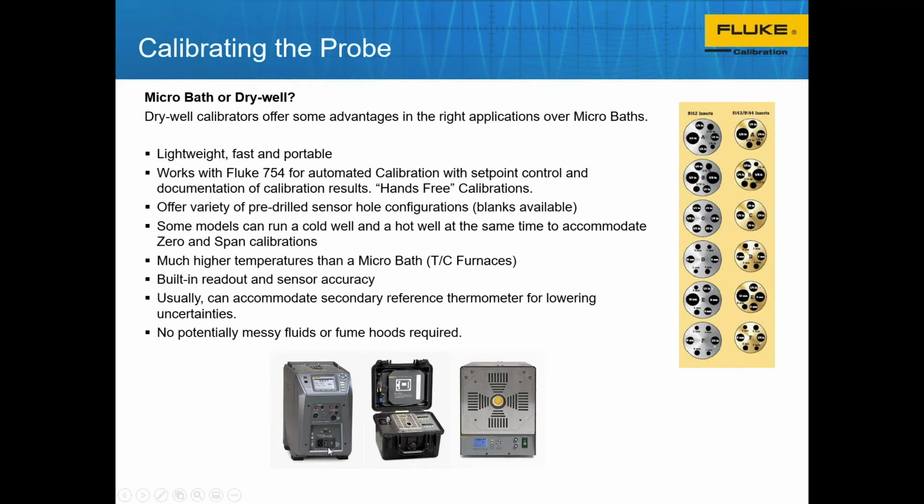We have some models that can actually run what we call cold calibrations, so below ambient or sub-ambient temperatures. They not only heat, but they also have cooling capabilities. We cool them using Peltier thermocouples, which is the same technology you have in those plug-in coolers you use in the summertime when you want to go camping and keep your pop cooled or whatever the case may be. You can plug this into your 12 volt outlet in your vehicle and it will cool things down. We use the same technology, obviously to an industrial level and accurate to the standards that we need, but we were able to pull the blocks down below ambient.